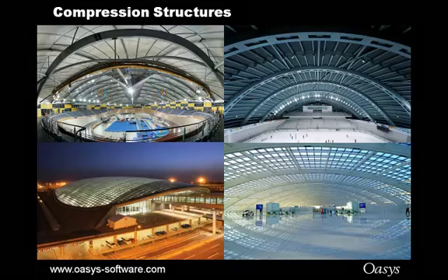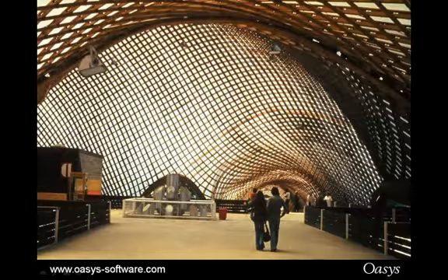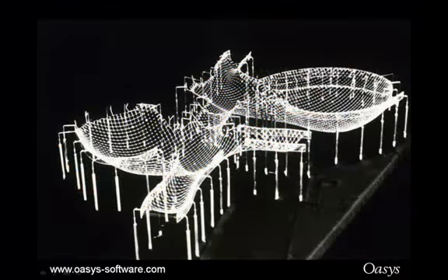These are quite regular, obviously. You can also use it for more organic grid shell type structures. This is the Mannheim World Garden Exhibition, and you can see from the inside shot, the structure is quite slim and slender, but it's very stiff under uniform load, but you still need some minimal bending strength for wind and snow. Now, this was designed back in '75, so wasn't designed using GSA.